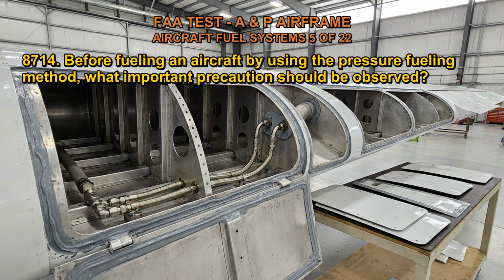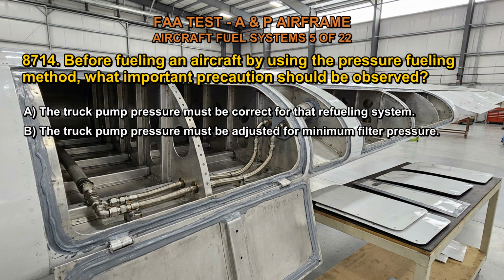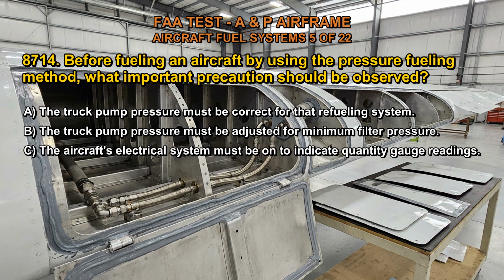8714. Before fueling an aircraft by using the pressure fueling method, what important precaution should be observed? A. The truck pump pressure must be correct for that refueling system. B. The truck pump pressure must be adjusted for minimum filter pressure. C. The aircraft's electrical system must be on to indicate quantity gauge readings. The correct answer is A.